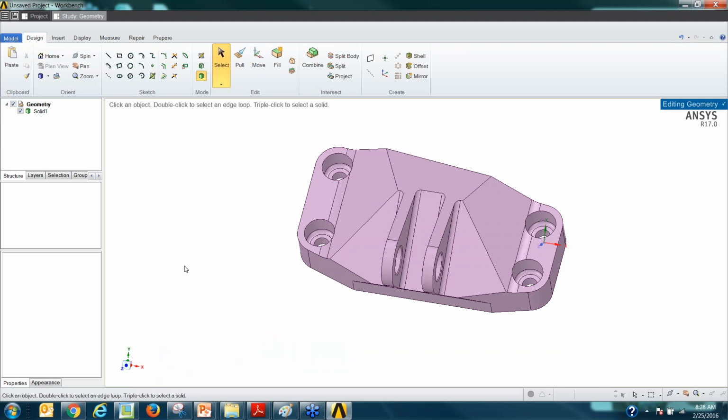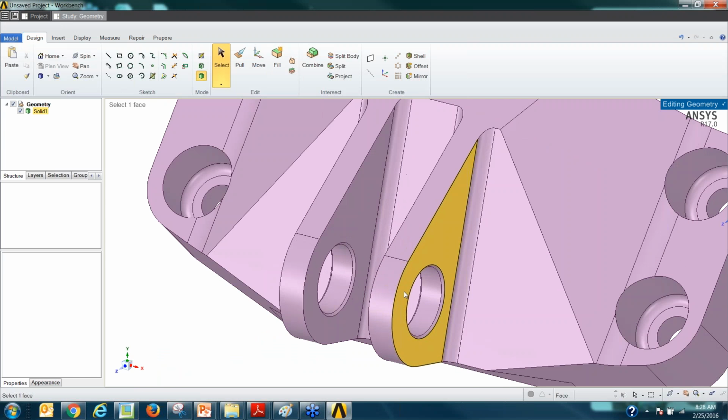So I do have an edit geometry option here. When I edit geometry, you see how within the same environment, Ansys allows you to do typical editing that you come to see in most CAD tools, right? I'm able to move, push and pull, edit the radius, things like that. For example, in here, let's say I want to select a few surfaces.